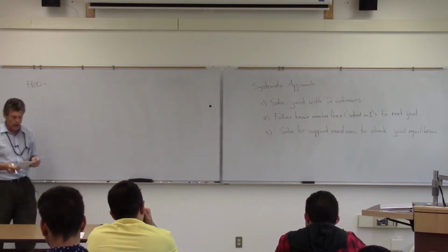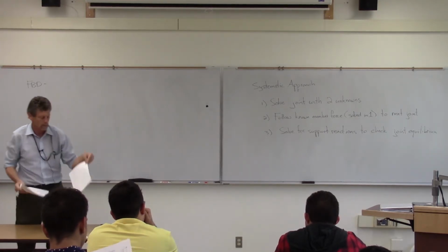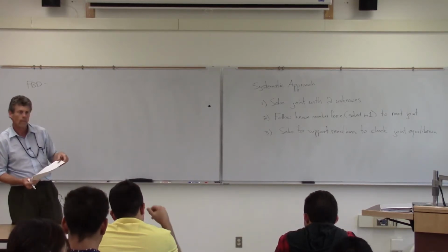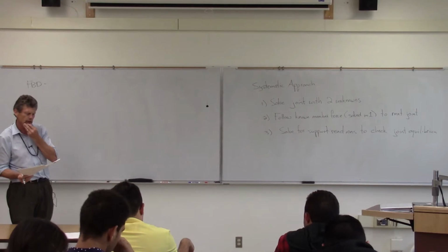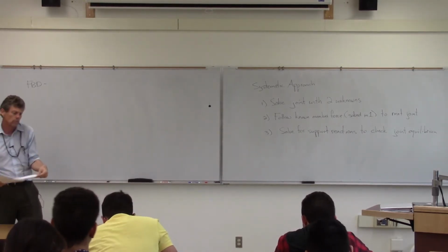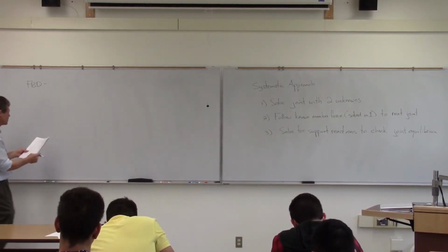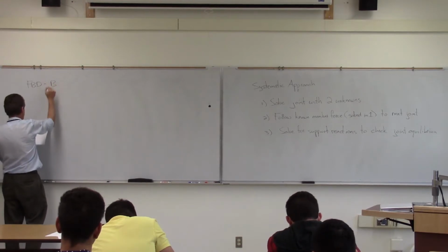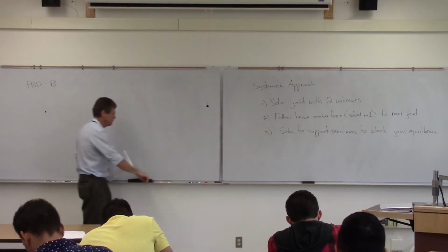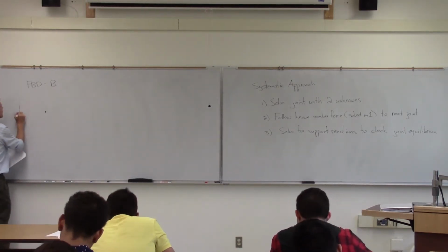Okay, now we'll note in our problem there when we look at joint B, how many unknowns are there at joint B? We've got one known force at 84 kilonewtons, and then we got two members attached to it, two unknowns. So that's going to be one of those problems. It's going to be real nice that we're going to be able to start at B. So our free body diagram looks like this. It's a very hard one if you don't get the circle quite correct.